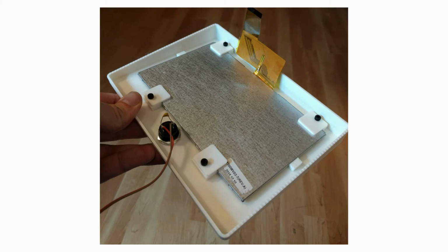I had to add a clock and a few other things. But also, like you said, the manual for these things is not awesome. There's a different mode where instead of giving horizontal and vertical retrace, you have a data enable pin or something, which is very badly documented. But this is what I ended up using to save myself a pin.